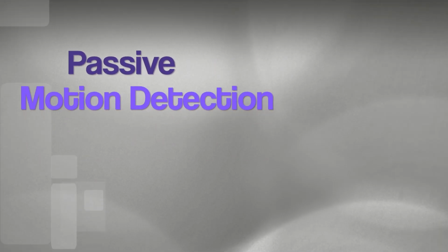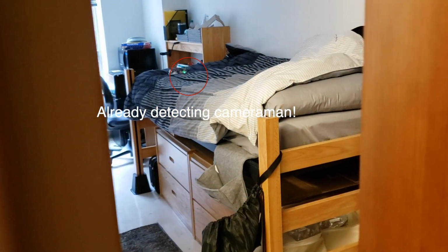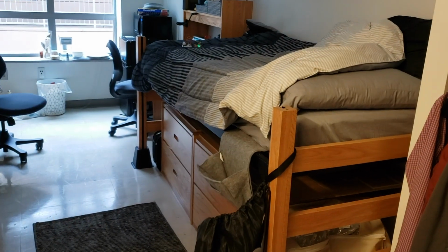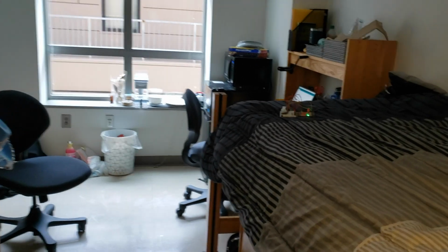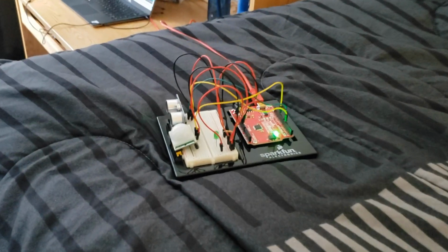Passive motion sensors, on the other hand, do not send out signals. They simply detect signals already present in the environment. One common signal that is an indicator of motion in life forms is simply heat, and this is why passive infrared sensors quickly became the most common form of motion detection for security purposes, starting in roughly the 80s. They detect infrared radiation produced by humans, or put more simply, they just receive thermal energy, and a high enough change in energy level will trigger the sensor.